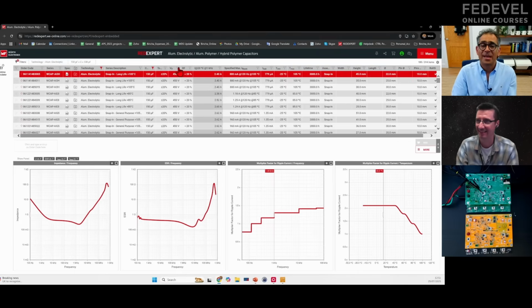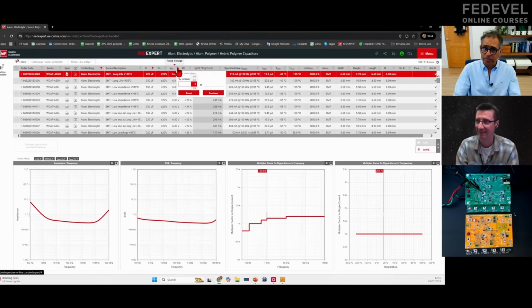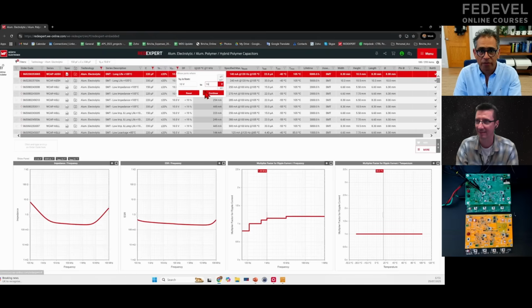Then we said that the voltage stress was 5 volts. We allowed 30% margin, which came to 8 volts. And then we said, you can't find 8-volt ones. Let's get one between 10 or 16. So again, I used the tool to narrow it down. And if I go from 10 or 16, it goes down to 82 of them.